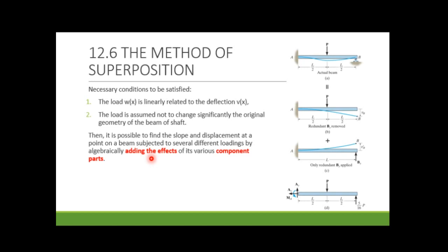I think my definition is not easy to tell. Okay, I think I can easily show it in this figure. For example, if we have a force like this, this is a statically indeterminate system because point A is the fixed support and point B is the roller support. The number of unknowns is 4, so we don't know how to calculate the reaction forces statically. But we can use the method of superposition. We know at point B the deflection is equal to 0.